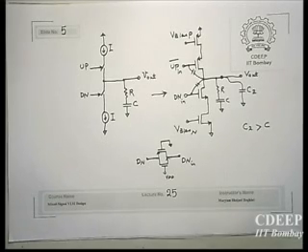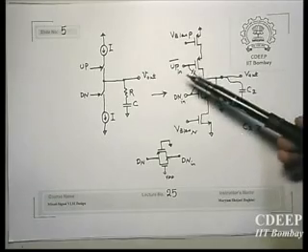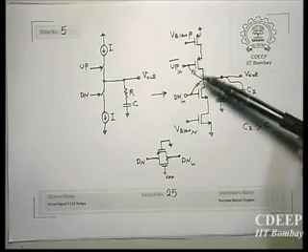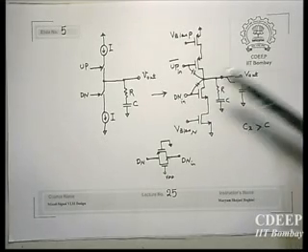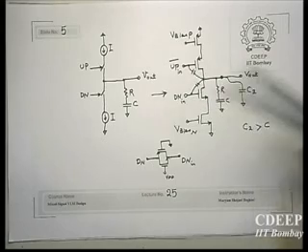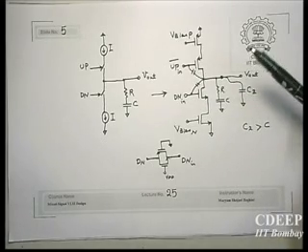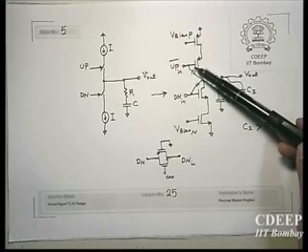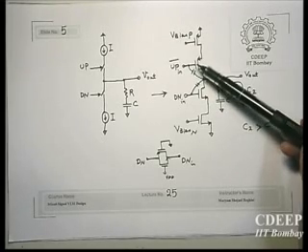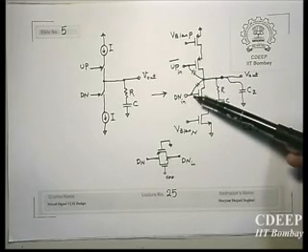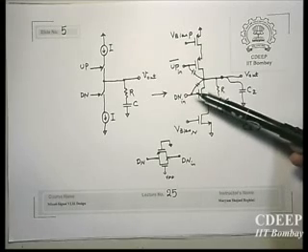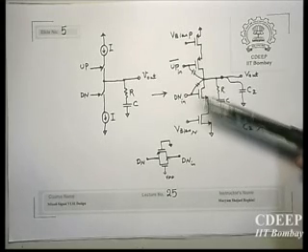Otherwise, what will happen? Because there is a delay between up and up bar. Suppose you have the case where up and down both should be high and therefore no current should be given. But because up bar arrives late, this still is not high, so it will remain low. Yeah, like this.